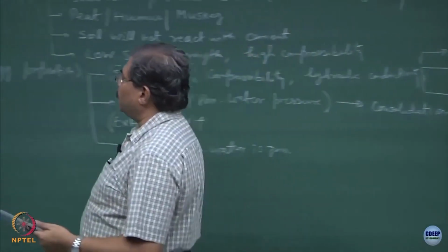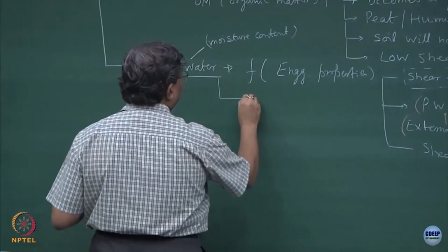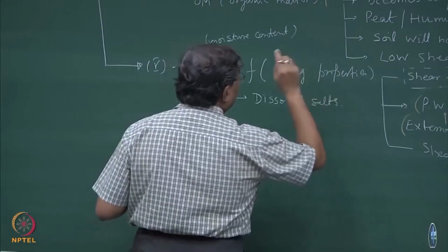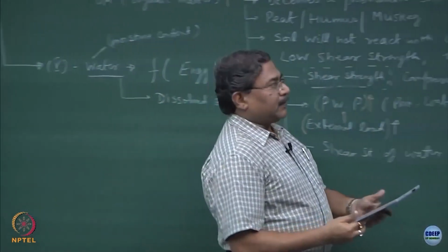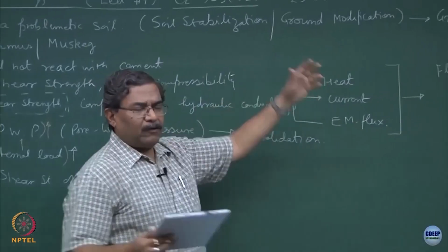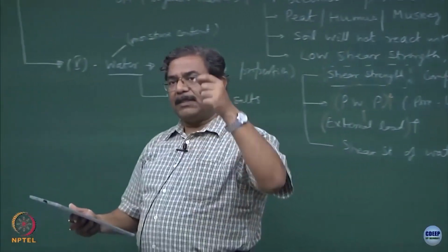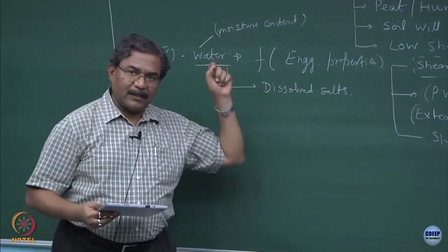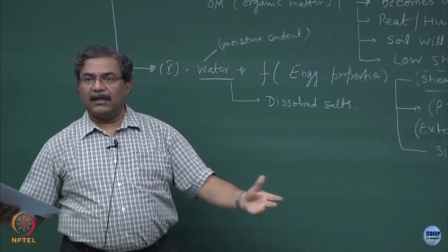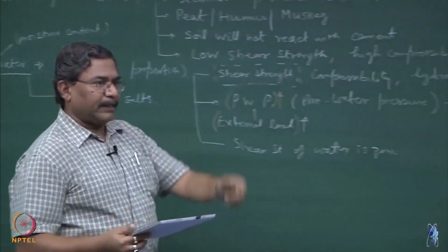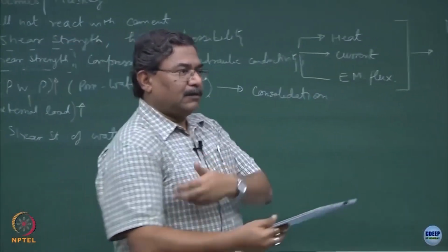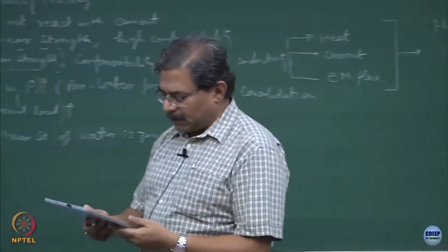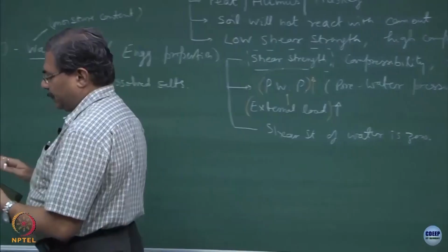Water is the carrier of dissolved salts and minerals. Now, I think you can realize this. If I want to stabilize or modify the soils, what will I be doing? I will take some cement slurry. Water is the carrier, and I am injecting dissolved salts into the system to make it strong. Very similar to what doctors do by injecting an ampule or some injection into your body if you have some deficiency or disease. There is a lot of similarity between all these things.